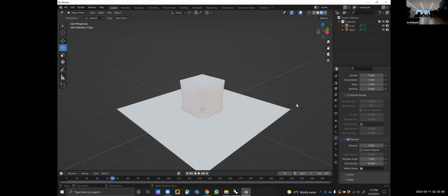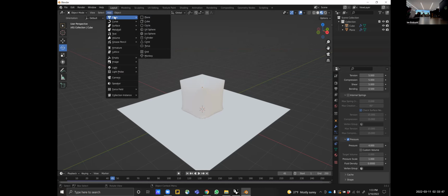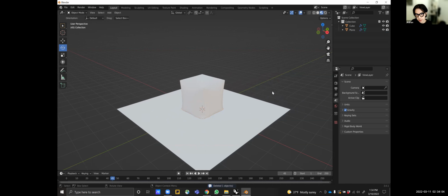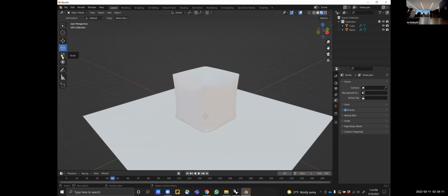How did you add the floor? Yeah, sorry. Okay. So you go add up here by the object mode, add, mesh, plane. I mean, it could be anything. Plane's just an easy geometry to start with. And then again, to scale, while it's selected, you'll just click S, and then you'll drag your cursor around and you'll see the preview of the geometry getting bigger. There's also a scale thing on the left where you rotate and gumball are. Yes, true. Yeah. Where's that? Here. Scale.